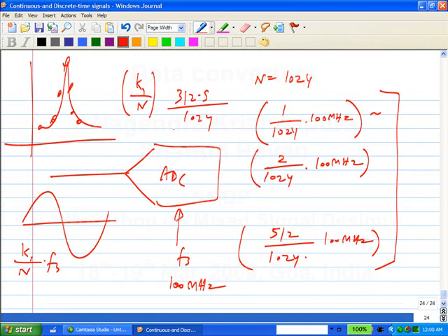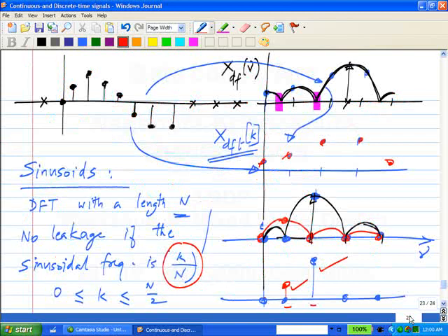No amount of trial and error will get you there, right? Once you have chosen the number of points, n, these points are fixed, the points at which you compute the DFT. So if your stuff is somewhere here, there is nothing you can do. Now if it is exactly in the middle, maybe when you double the n, you will hit this point, but it may not be exactly in the middle. So you don't know. But generally, yeah, increasing the number of points helps. But let's say you increased it to the maximum that's possible. What do you do after that?